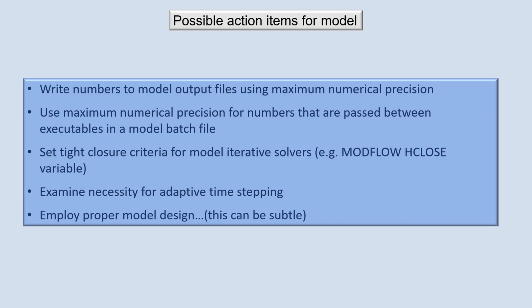Say, for example, a model only writes to its output files with 3 significant figures. When we vary a parameter incrementally, take one number from another, then if those numbers are very close together, perhaps we've lost all those significant figures in the differencing. That causes model output granularity. If we can adjust the model output protocol in any way, because the model gives us some control over this, we should ask that model outputs be written to the model output file with maximum precision.